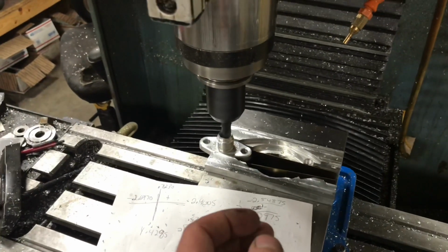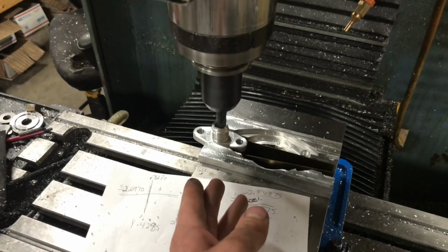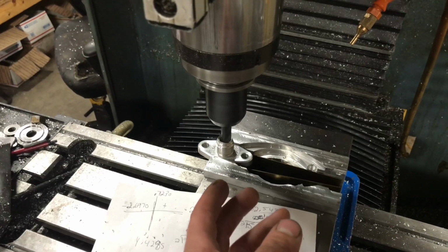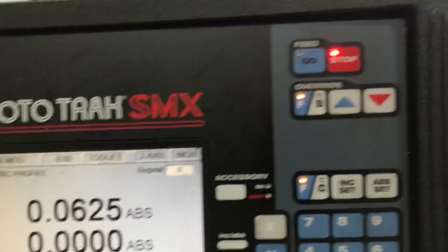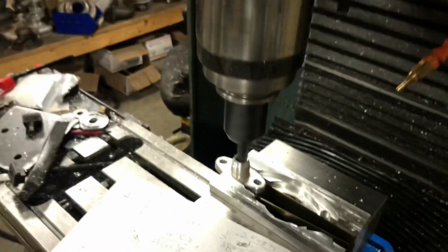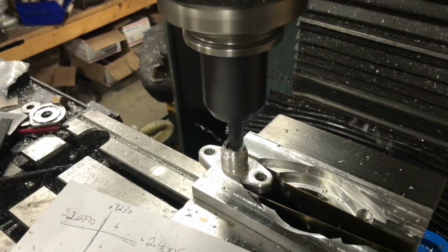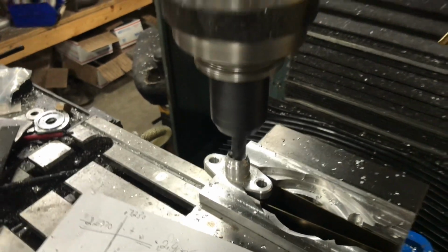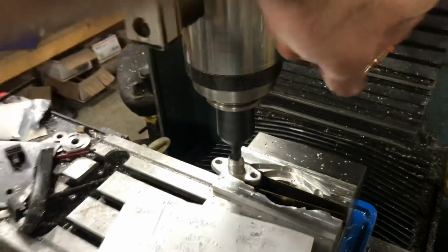But I'm cutting in the same position, the same part, multiple times, and this is the only thing I'm doing. So I just went ahead and put Z deeper, another 100 thousandths, and I'm going to press go and run this program. So let's just keep running it until we're all the way to the bottom.